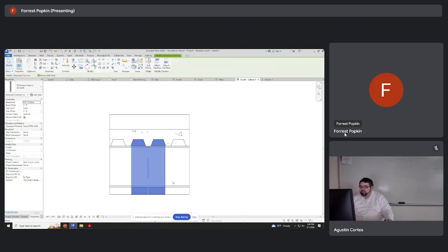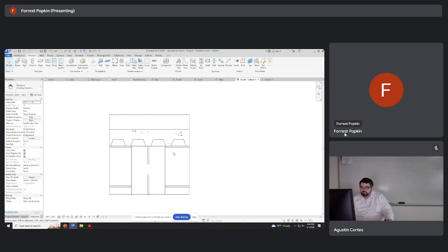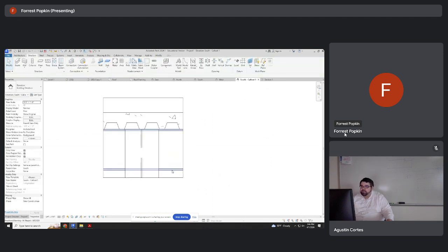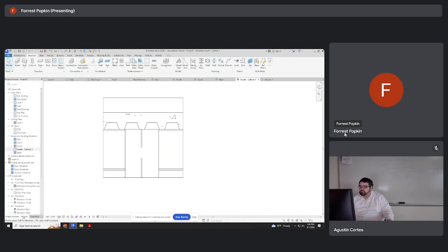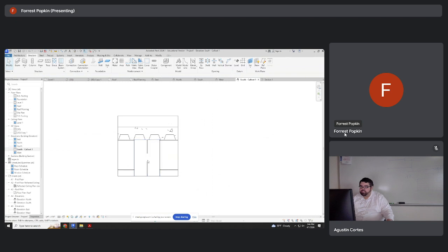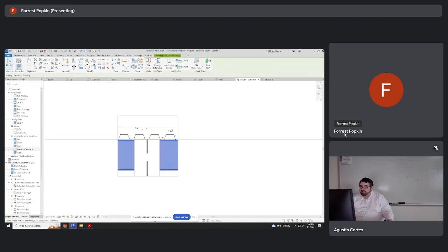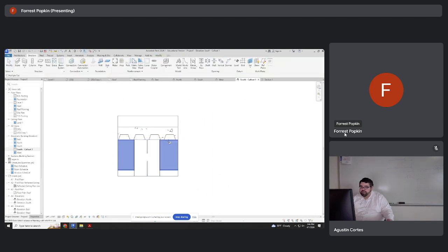Similarly, I want to offset my column. -5, whoops, to -5. Now it looks like I lost my coping though. My coping detail. So the question is, how do I get that back? Well, again, go to coping. Where am I coping? This guy. What am I coping against? This guy. I guess I moved the section. I don't know why it's not showing up.